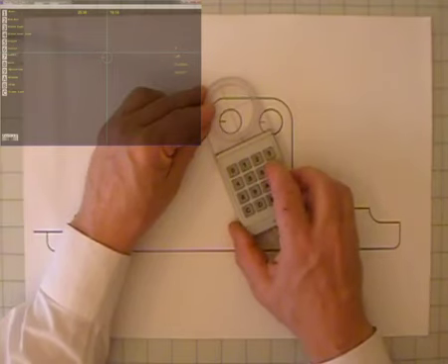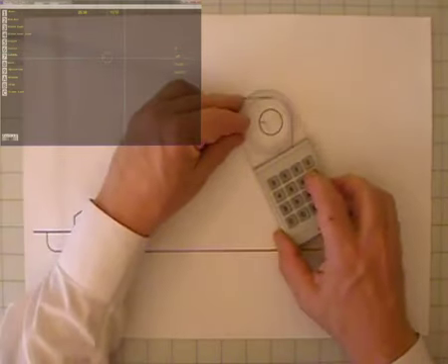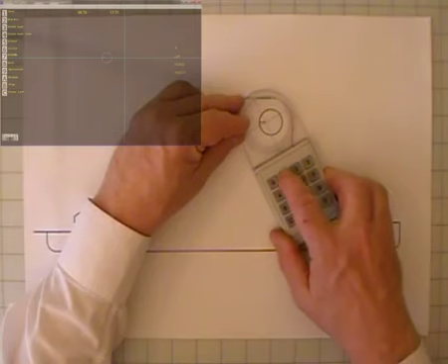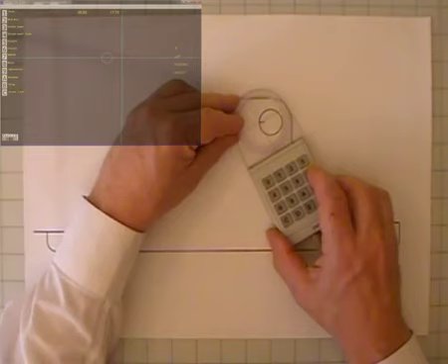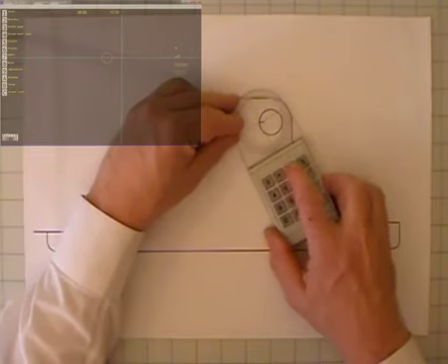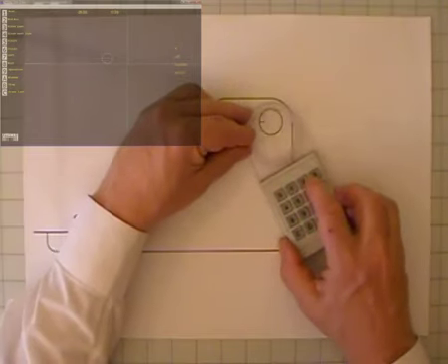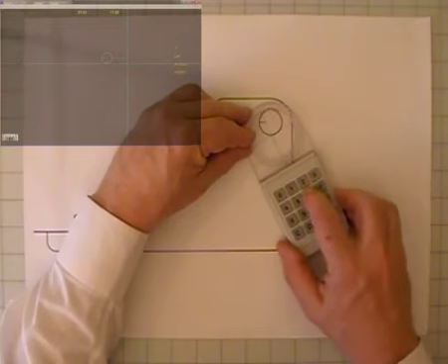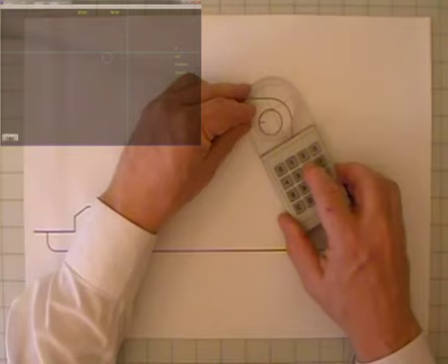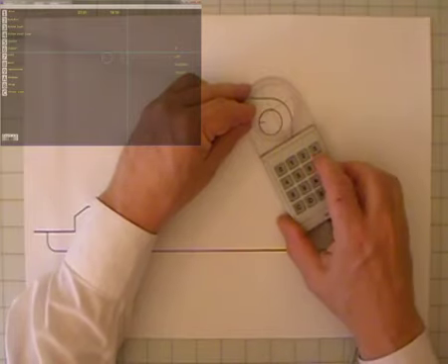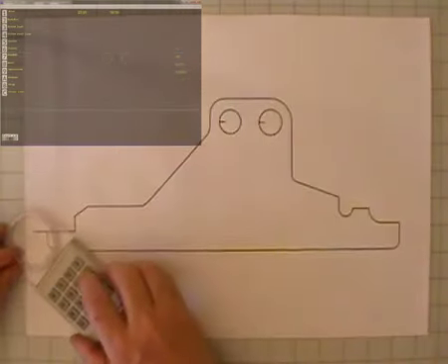Now button number 7 to turn the torch off and wrap it to the next circle and repeat the sequence. Note carefully that the sequence of the points gives the direction of the circle. With curve left, you must pick the points in a counterclockwise direction for a hole. Now to cut the outside. Button 7 to turn off the torch and go back into rapid mode.